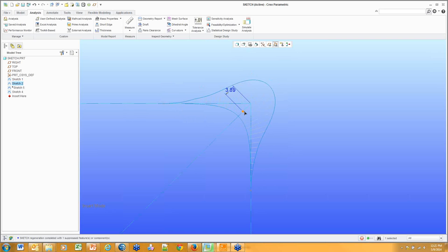Is there an exact value we can give it? Not really. You know, here we're simply using this graphical tool to figure out the smoothest transition that we can get from flat to a round. Okay, and then at this point here we can go ahead and complete the operation, and we can use this curve to create solid geometry. The beauty of using this versus a C2 round is you have a lot more control over its final shape.